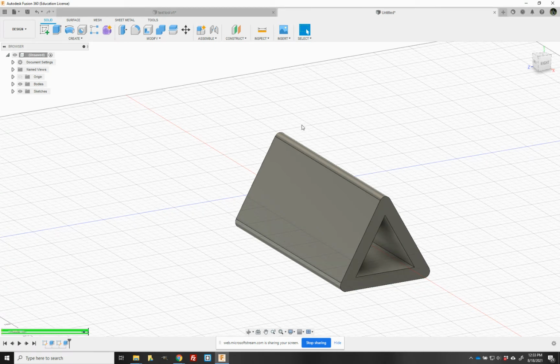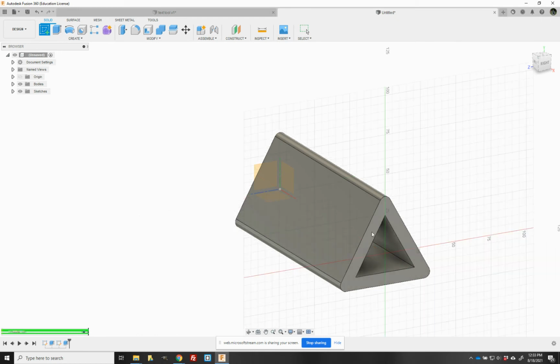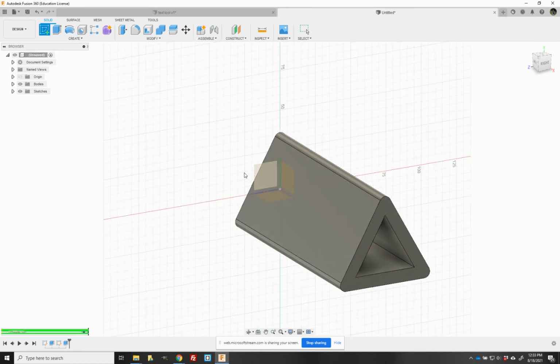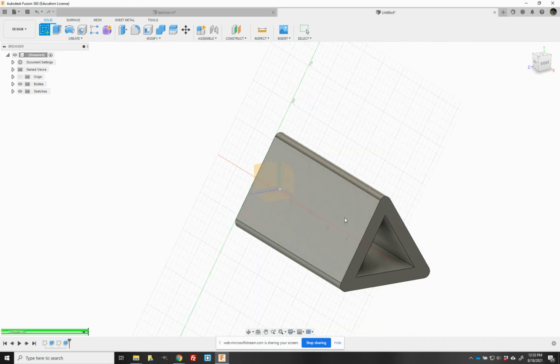We are going to add our text to this face now. So let's create a sketch. Once again, I'm going to select this face. Do not select over here where the planes are shown. If you click on space that is occupied both by a plane symbol and the face of the object you want to sketch with, it will default to the plane.